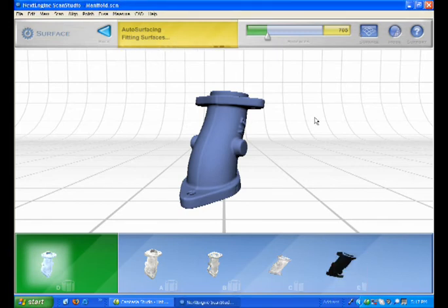What you can do with the IGES file is bring that into any version of SOLIDWORKS. You could bring it into SOLIDWORKS Office, Office Professional, or Office Premium. Why this is so nice is that you don't have to have SOLIDWORKS Office Premium to bring an IGES in. What the IGES allows you to do is basically reference the mesh in SOLIDWORKS. You can use it in your assembly process. You can shell it, you can cross-section, and so forth, and basically use it as reference in your design.